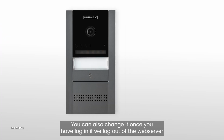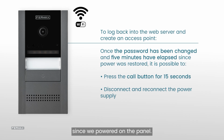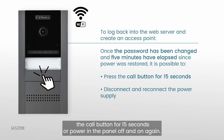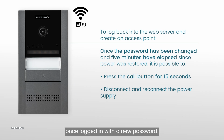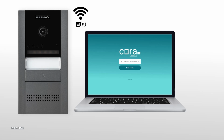If we log out of the web server now, once the password has been changed and more than 5 minutes have passed since we powered on the panel, we can log back into the web server and create a new access point, either by pressing the call button for 15 seconds or by powering the panel off and on again. Once logged in with a new password, we can continue to change the panel settings.